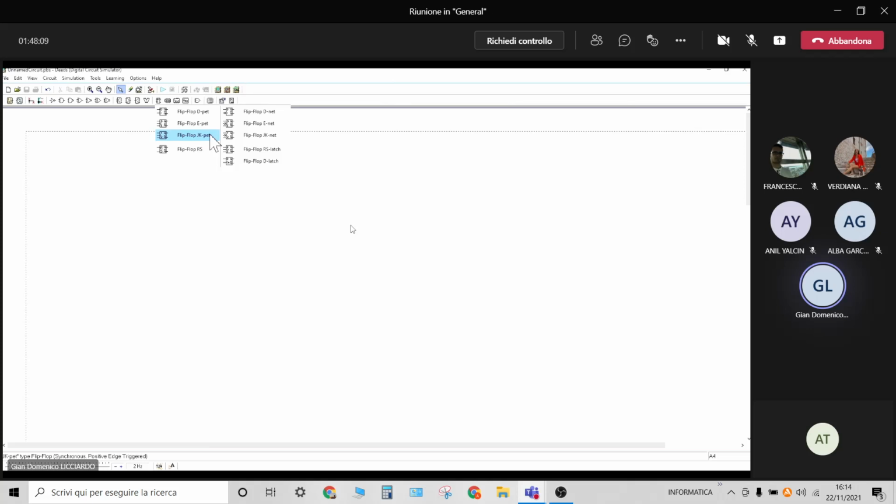Since now we have a master-slave configuration that globally behaves like a flip-flop, just to distinguish this from the previous one, from the flip-flop that can be hold and transparent, we say that this new flip-flop is edge triggered. Namely, it is triggered on the edge of the clock.